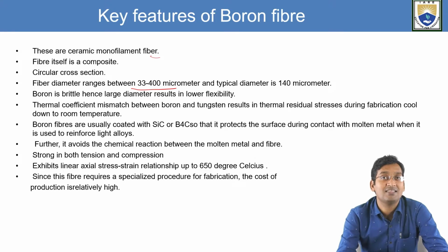Boron is brittle, hence a large diameter results in lower flexibility. The thermal coefficient mismatch between boron and tungsten results in thermal residual stresses during the fabrication cool down to room temperature.